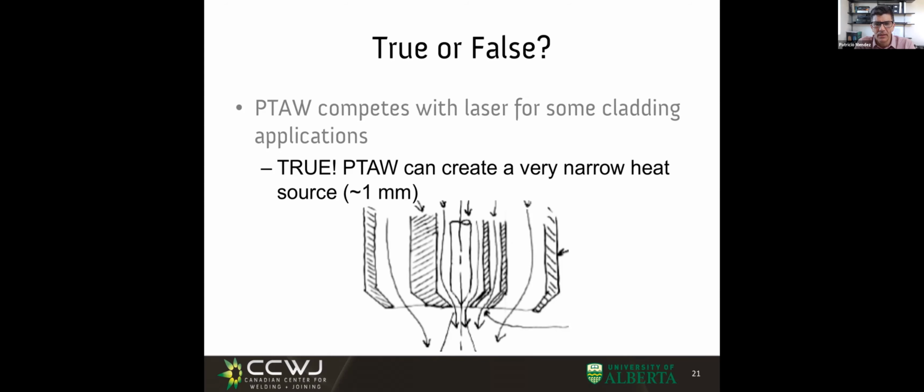PTA can create this very narrow heat source that competes with lasers. Now, here's the funny thing. Although PTA can compete with lasers in many aspects, lasers require such a high level of automation that typically a laser operation has often been preferred over a PTA just because those people in the laser are so careful and so automated. But in many cases, PTA could do it too.